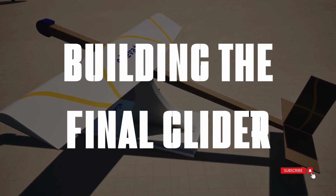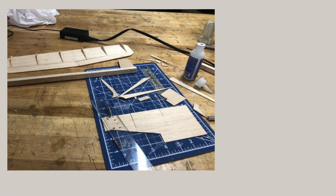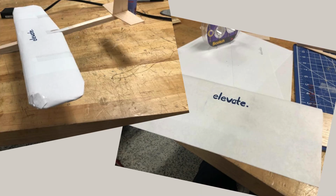I created the final design, which I named Elevate, with a wingspan of 40 centimeters to maximize the wing area without breaching the 16-inch limitation. It also had a total wing area of 396 square centimeters. I made the wings using 2 different balsa pieces, so I decided to angle the back piece of the wing like flaps, rather than setting the whole wing at an angle of attack. I created the airfoil by cutting out balsa ribs and covered them with paper.